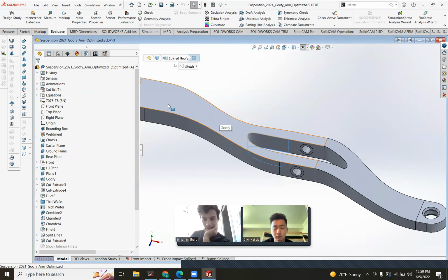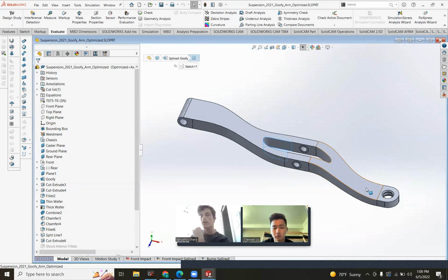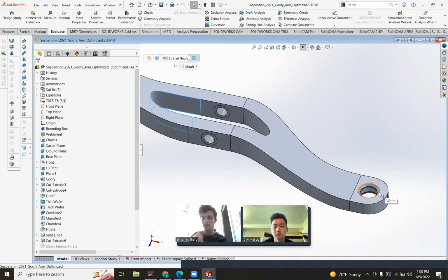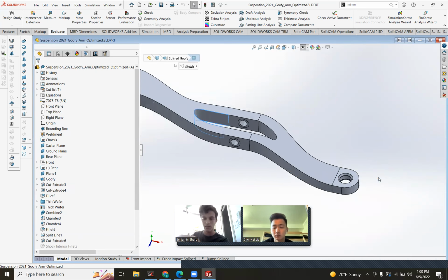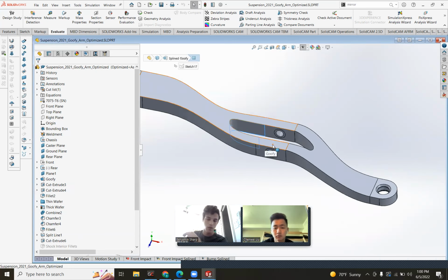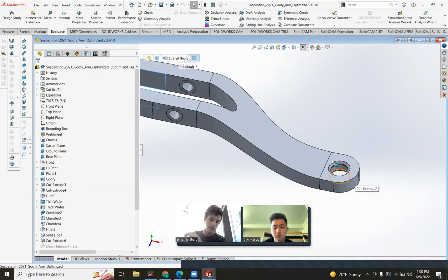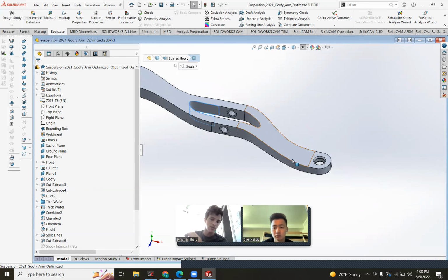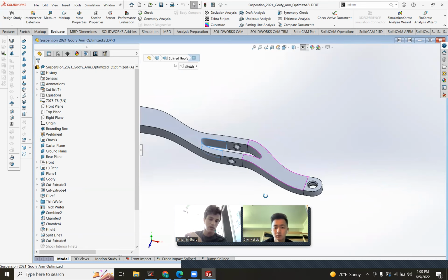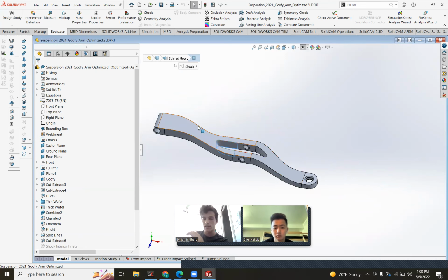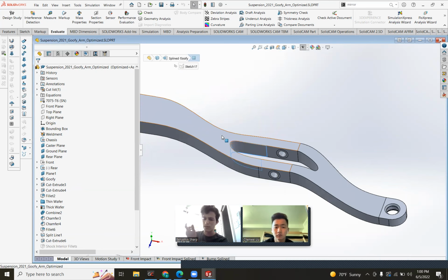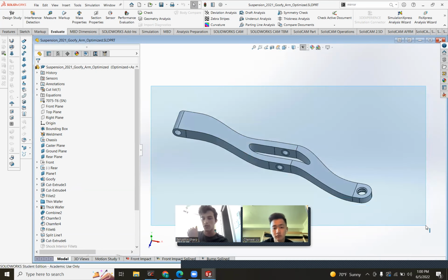It has more cutouts here because it features no spherical bearing, which is what caused such high stress in this part. So the one we cut ourselves has no spherical bearing, which means it can be thicker on the end so that it's the same thickness. And that also means we need more weight saving cutouts. But it was 30% lighter than this one, which is what we made for 21. Or what we run on 21.